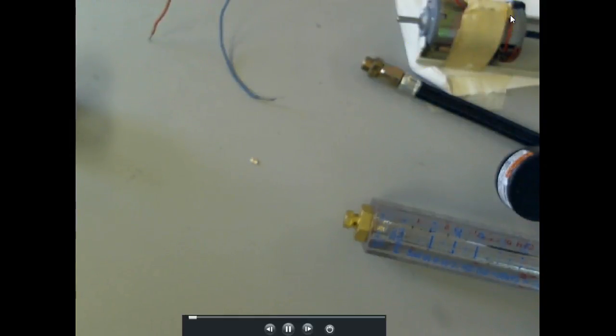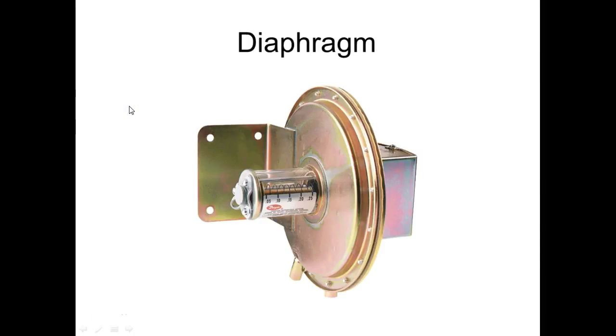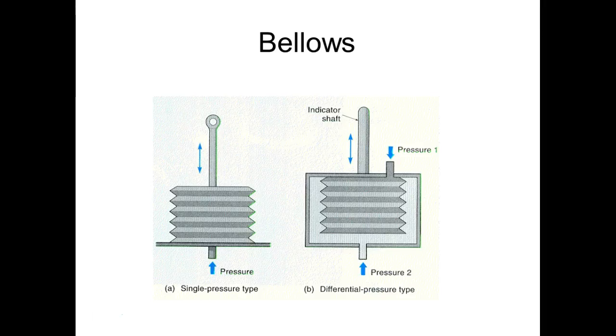It did. They had a diaphragm on there. But notice if the diaphragm's in the center, then it can not only sense pressure, it could also sense a vacuum. And that was what was on your carburetor, it was sensing the vacuum. I forgot about that. That's automatic, of the 50s. Before that, you had a rod. What would happen is once your car cranked and it created a vacuum, it would open up.